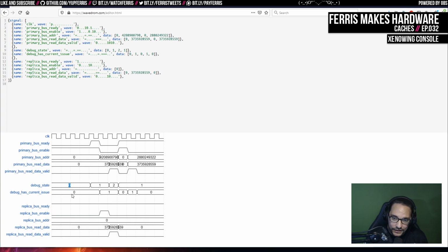And by the way, the reason I invalidate on reset, or spend a bunch of cycles doing that, is because this is an internal memory, and on FPGA you can actually load those kinds of memories with some contents at startup. So I actually don't need to do this, but I want to implement this invalidate feature because I need it for the system to behave correctly anyway. So I thought, why not leverage that and do it at startup too, which is more like what an ASIC would have to do. But I don't have to do that on FPGA, so I might remove that. Anyway, it spends a bunch of cycles clearing that, and then you can see it signals that it's ready.